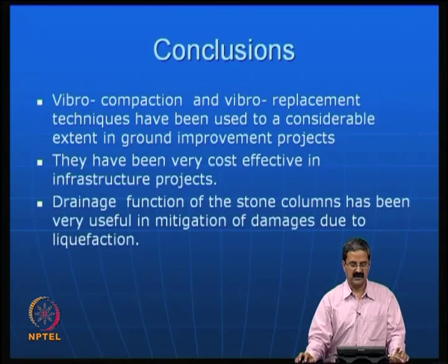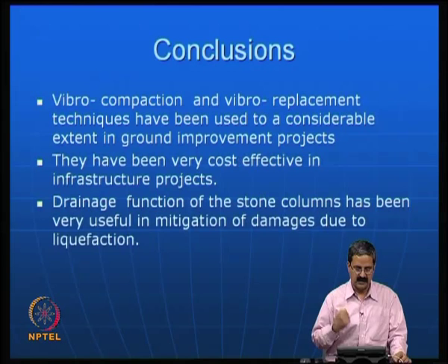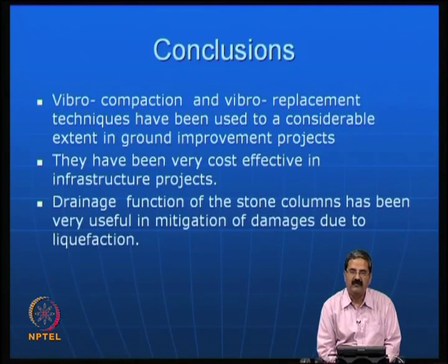So what I will do is give some conclusions now and also show you some case studies. For example, we have vibro compaction techniques and vibro replacement techniques. They have been used to a considerable extent in ground improvement projects. They have been very cost effective.